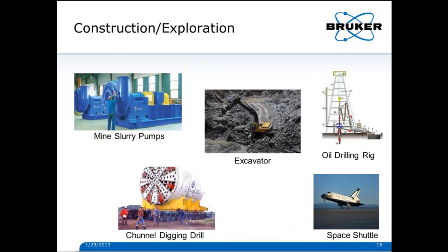In the construction or exploration area, when we transport slurry from mines, there's a lot of erosion happening in the mine pumps. Very large pieces of equipment can be placed out of service because of just 10% of the entire mass is worn, but it doesn't function anymore. When we talk about abrasive wear, we have an excavator which is experiencing 3-body wear, so we have loose pieces because of the wear. Or the channel digging drill is 2-body wear, where we're just grinding into rock and there are no loose pieces initially in contact.